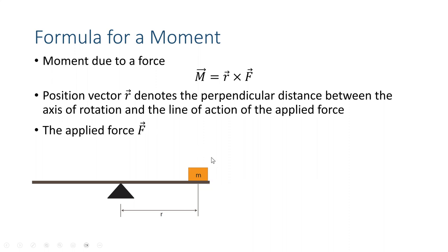And so what's important for us to take away from this discussion today, relative to our boats, is that the line of action is a perpendicular line, and the distance away from that line of action to our rotation point is the length of that moment arm. So we've got a force times a distance is equal to our moment.